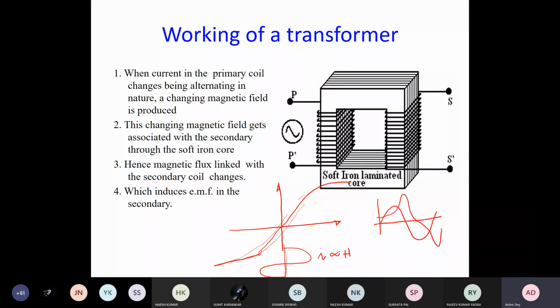This is your phi and this is your I. Then it will have a lot of harmonic content, and because of that there will be losses. That is responsible for the core losses, and if you take a bigger area, the flux will be more distorted from the sinusoidal, so it will have more losses.